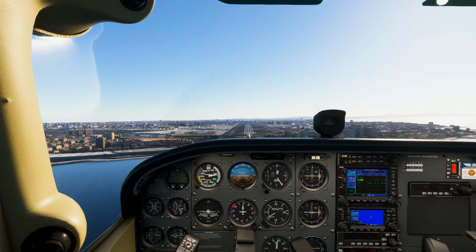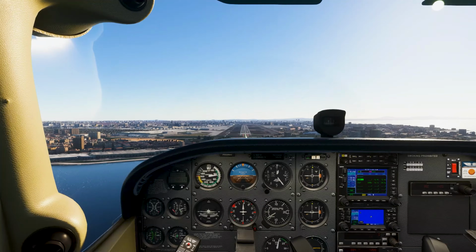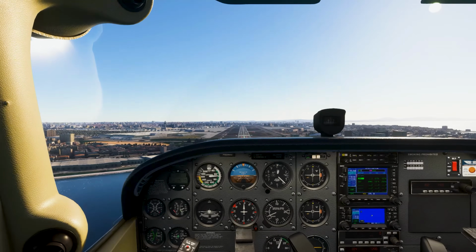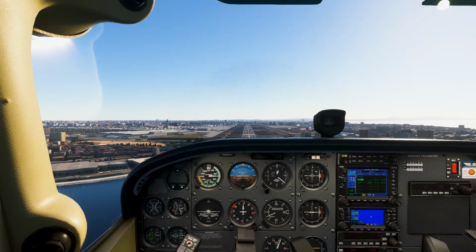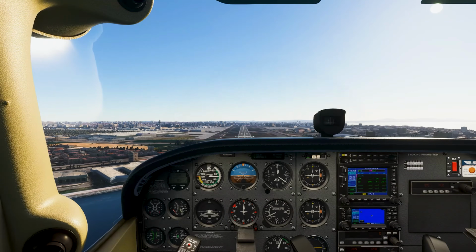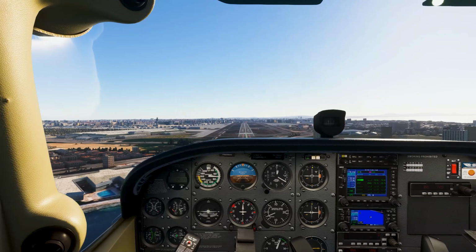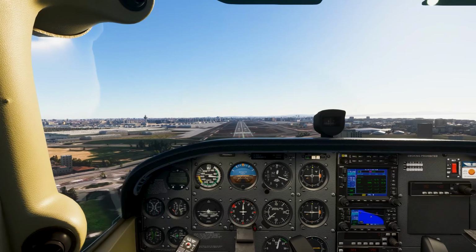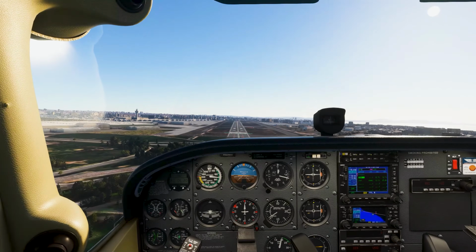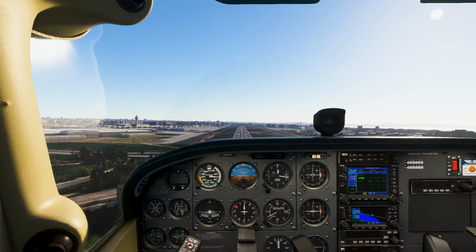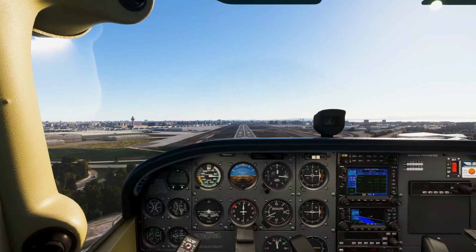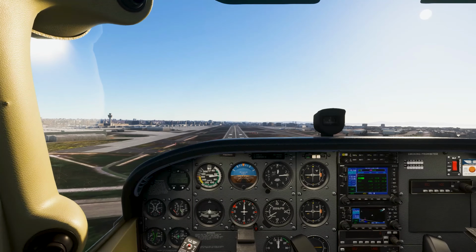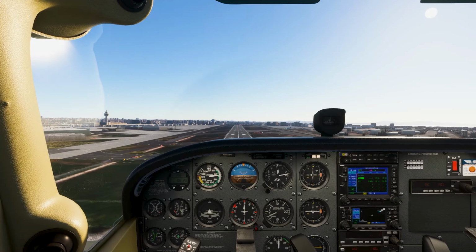In other words, your aircraft will flash on their screen, indicating that you are sending an ident signal, an identification signal. The ident function is particularly useful when the airspace is busy or when the controller needs to verify your identity on their screen. Always listen carefully to ATC instructions and respond promptly when asked to ident. Luckily, it's easy. When ATC asks you to ident, just press the ident button on your transponder. That's it. After you press ident, they'll find you on their screen, and it's business as usual.